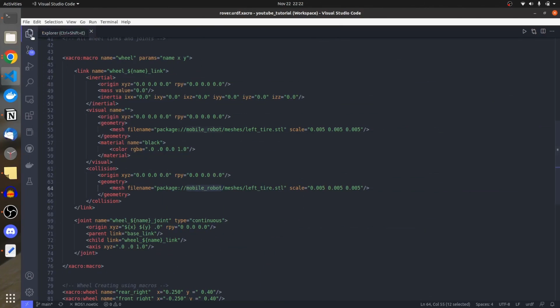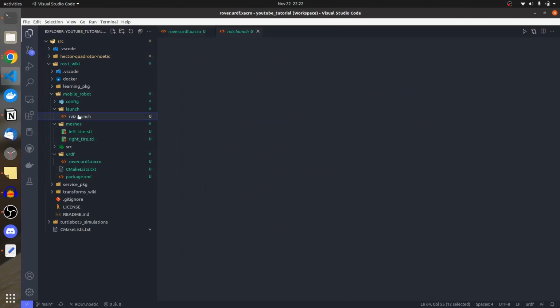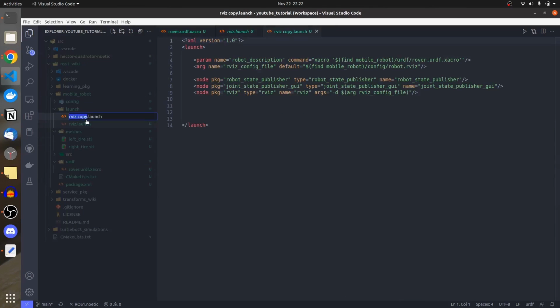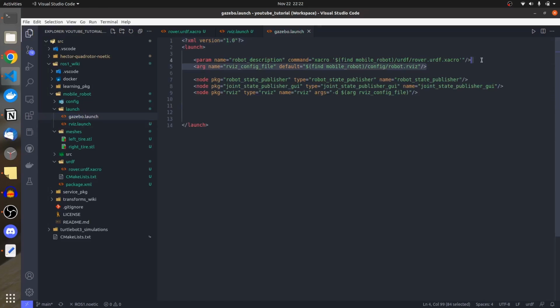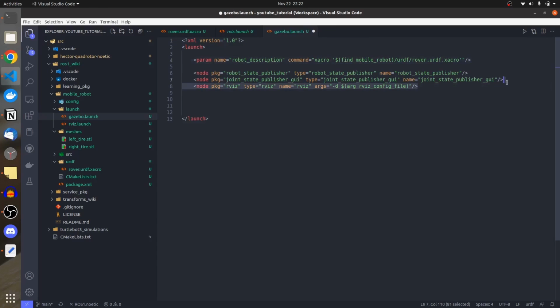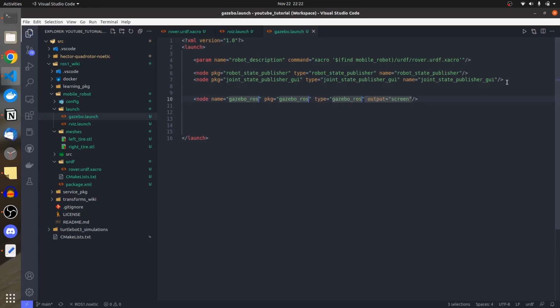The very first thing we need to do is to create another launch file, and that launch file is going to be the gazebo.launch file. We don't need ROS for that, and I am going to remove the ROS GUI. One node that we need to add is a gazebo_ros node, and its type is going to be different. Package is gazebo_ros, type is spawn_model. That spawns the model into our simulation, but the simulation is not there right now.